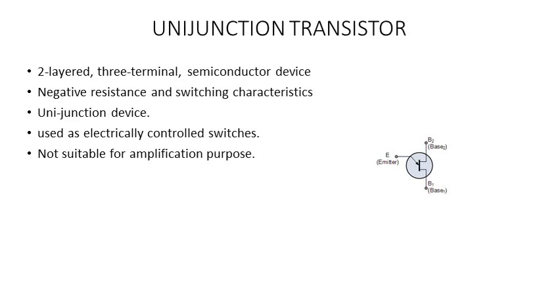When you connect it in a forward bias, the capacitance that is formed is called the diffusion capacitance. When you connect it in the reverse bias, the capacitance that is formed is called the transition capacitance. The diffusion capacitance usually restricts the switching speed, and the transition capacitance decides the frequency of the reverse switching operation of the diode. So a smaller value of these capacitances is required for higher frequency of operation of the diodes.